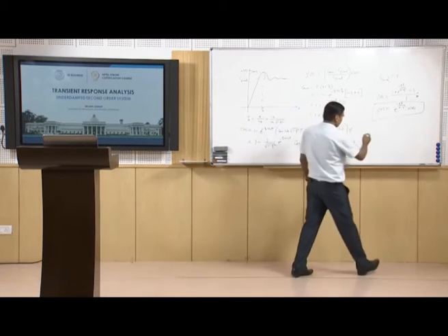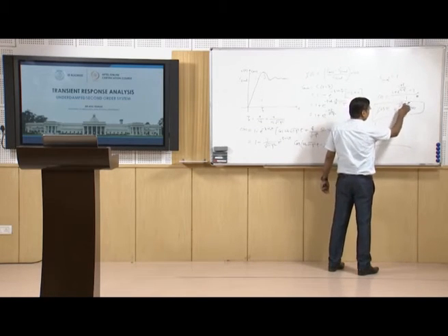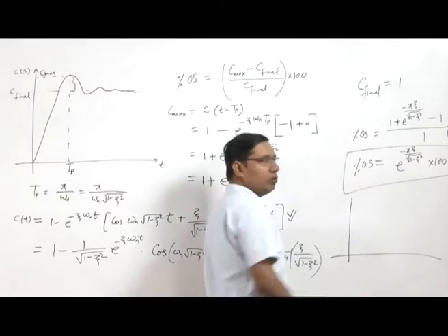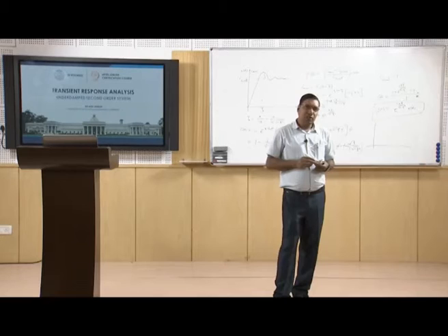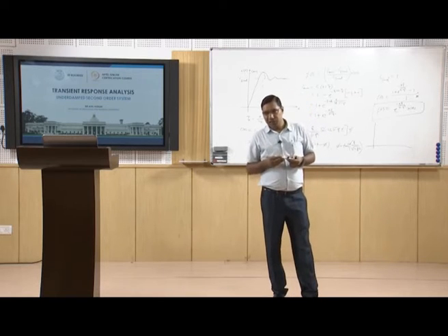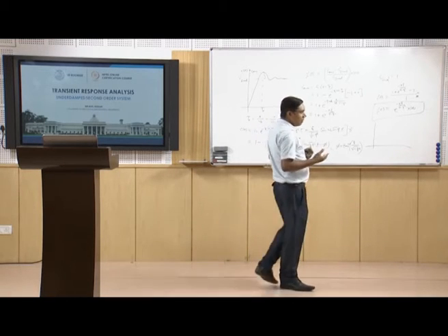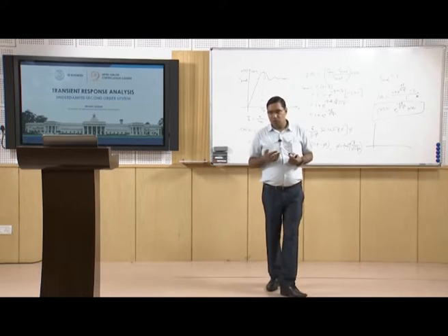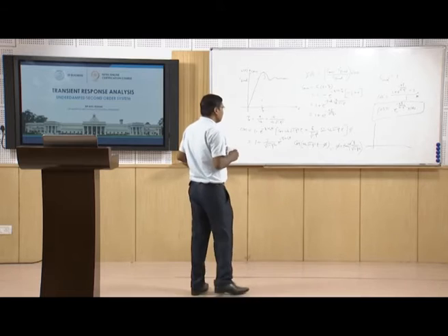When damping is more, this quantity is less, so percent overshoot will decrease when the damping increases, and that is expected because the role of damping is to decrease the response amplitude of the system. Therefore, more damping means less overshoot, so less maximum amplitude of the system.